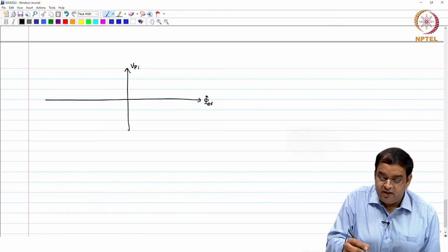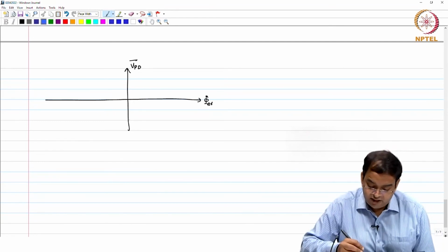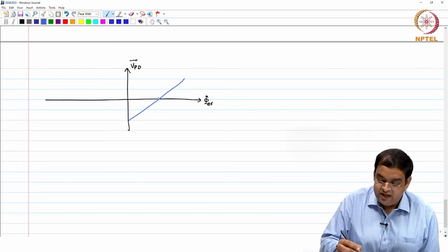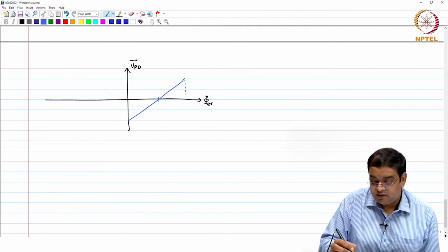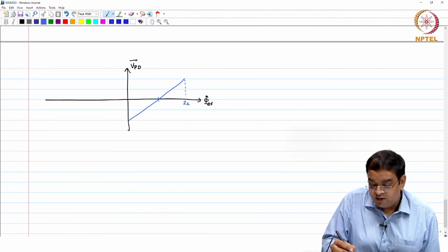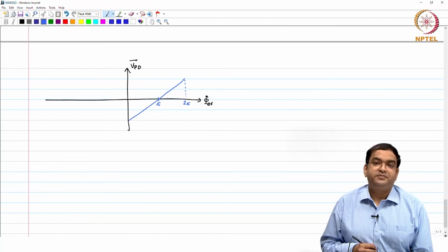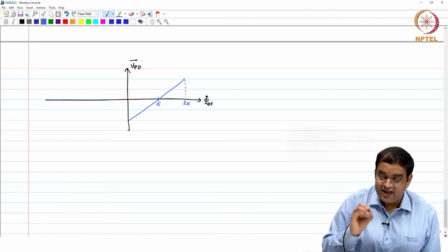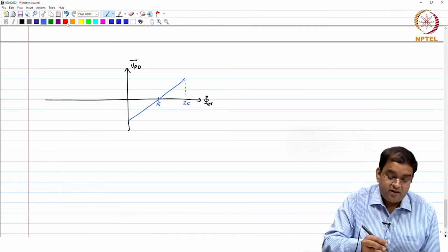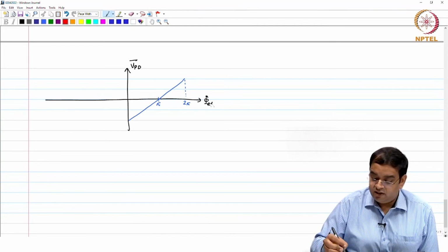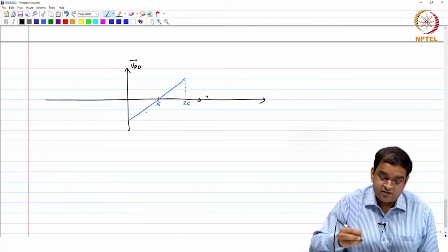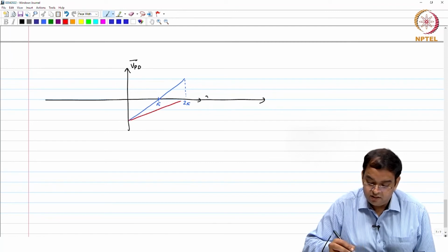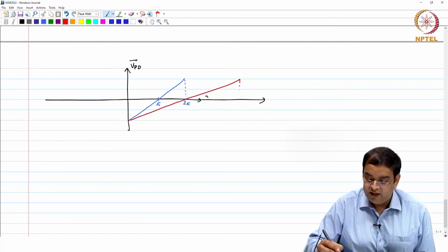VPD average. So, for XOR gate, VPD average, now this is going to be 2 pi and pi. VPD is the phase error measured between R and V signals, keep that in mind. And for our SR based one, that is going to be 4 pi.